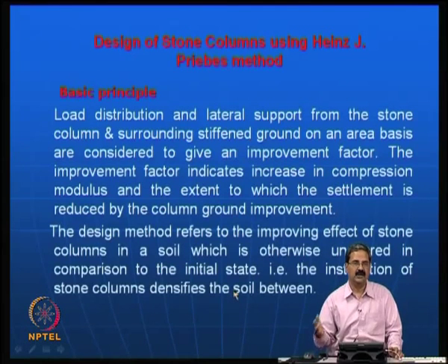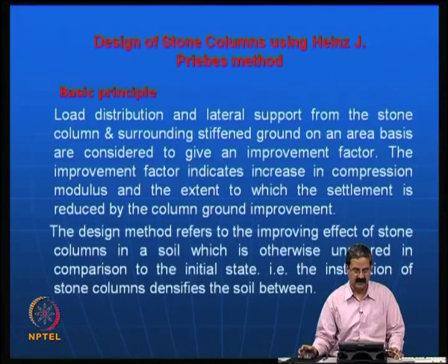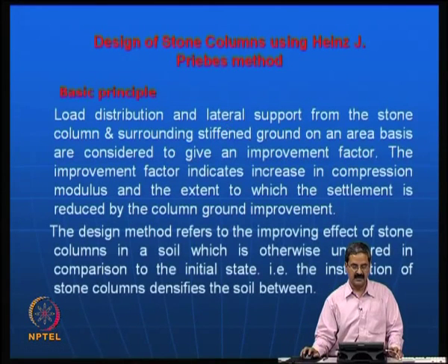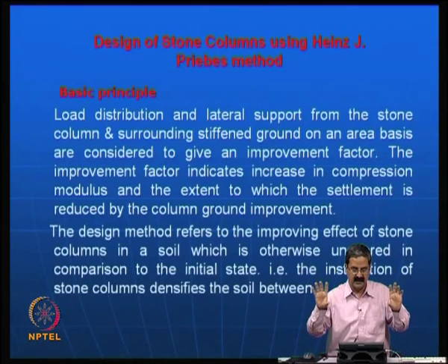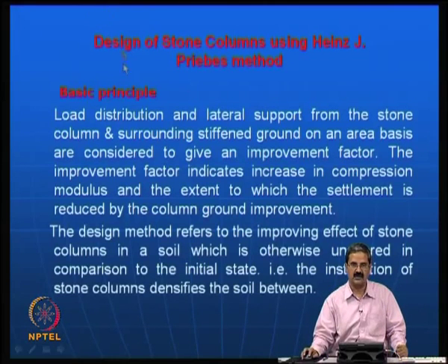So, still you need to come out with some sort of design method. Actually here in this particular Priebe's method, what we do is that load distribution is there and also lateral support from the stone column. So, that is how you have a stiffened ground, and it gives an improvement factor.